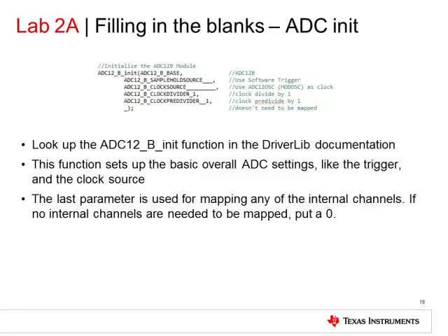Now let's talk about how to configure the ADC. The first step is to initialize the ADC using driver library. We would like to set up the ADC to use a software trigger. We also want to use MODOSC as the clock source for the sampling clock and not use any clock dividers. Use the driverlib API documentation to learn about the arguments that need to be passed to this init function. Once you have filled out your answers, check it against the solution.